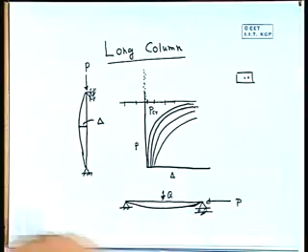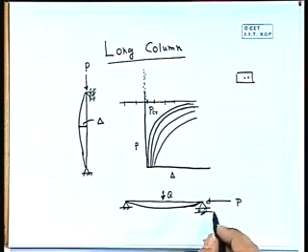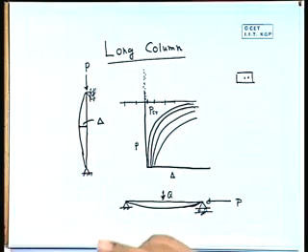I can give one example. Say Q equal to 1 Newton, P equal to 1 Newton. If we get some deflection and we make P and Q both double, the deflection will not be double, it will be more than double, right. So here the phenomenon is nonlinear for a beam column problem. Now at this moment we are not interested in beam columns, we may be later, but here let us take a pure column problem.